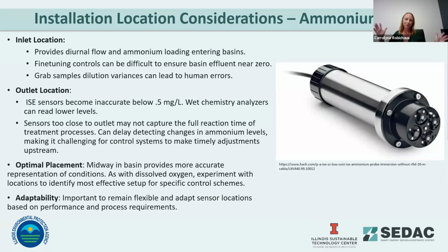You're going to full blow oxygen, and then you're defeating your purpose of energy savings. Of course, you can set an alarm in there to say, hey, my sensor is reading below 1 milligram a liter. I know that I'm not that low. I'll go clean it. Here's my alarm telling me to get somebody out there, maintenance, whatnot, to go out and clean that sensor.